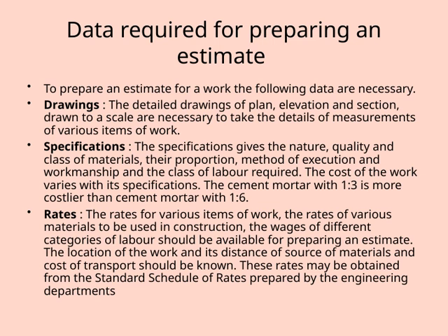Finally, rates are crucial. We need up-to-date rates for different work items, material costs, and wages for various categories of labor. It's also important to consider the location of the project, the distance from sources of materials, and transportation costs, as these all influence the overall estimate. Typically, we obtain these rates from standard schedules of rates prepared by engineering departments, which serve as reliable benchmarks. All of these components, drawings, specifications, and rates, are interconnected and form the foundation for accurate and realistic project estimates.